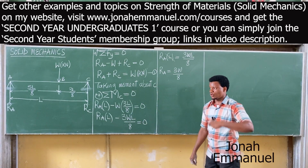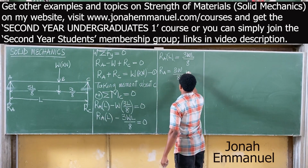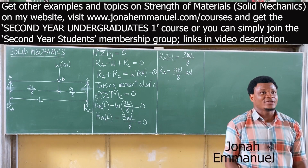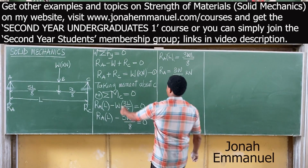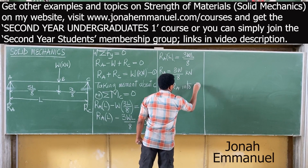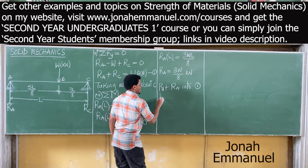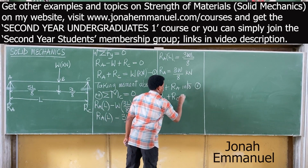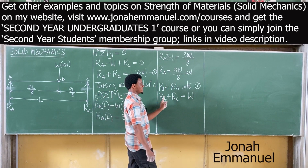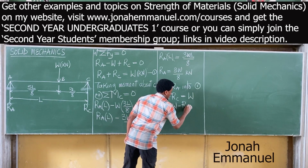RA is a reaction or a force, and it should be in the unit as given here, which is kilonewton. We've gotten the value of RA. Let's now get the value of RC. I'll now put RA into equation 1. From equation 1, you have that RA plus RC is equal to W. Okay, to get RC, move this man over here. We have that RC is equal to W minus RA.